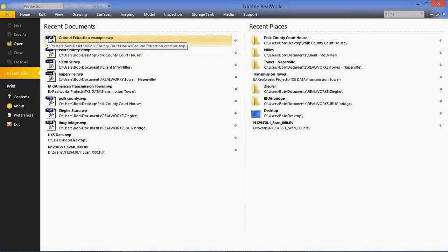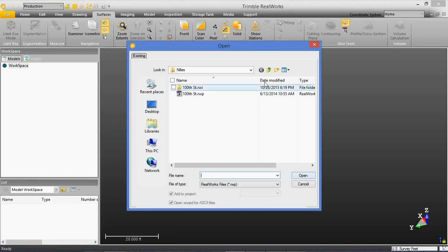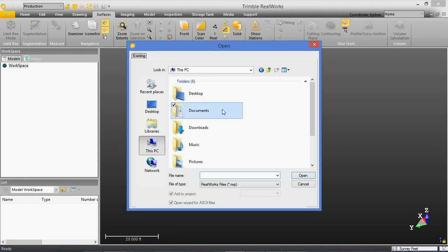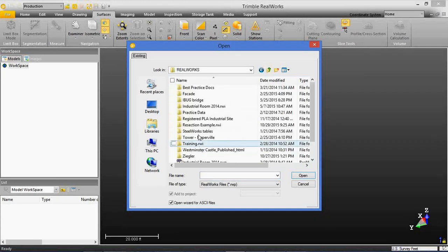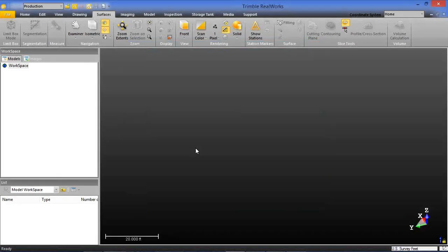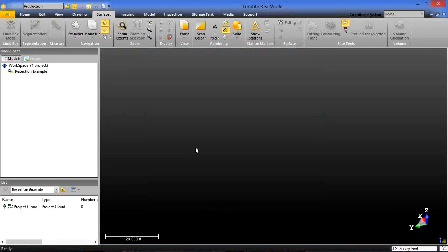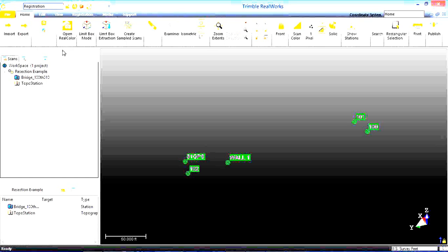I would like to say one thing about that ground extraction tool. That doesn't have to be just applied for just ground surfaces. It can be applied to if you were, say, doing a scan of a roadway or a parking lot, and you have people that are walking by and a bunch of cars in the parking lot. That same tool will automatically take out all of the people, the cars, the light poles, and it'll find the contour of the parking lot and the curb and keep that and throw everything else out. So it doesn't have to be just applied to ground surfaces. Right.